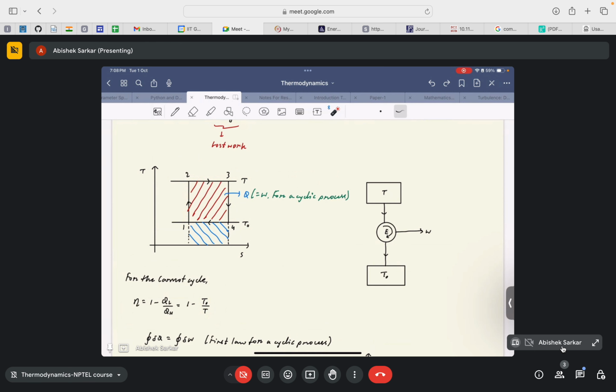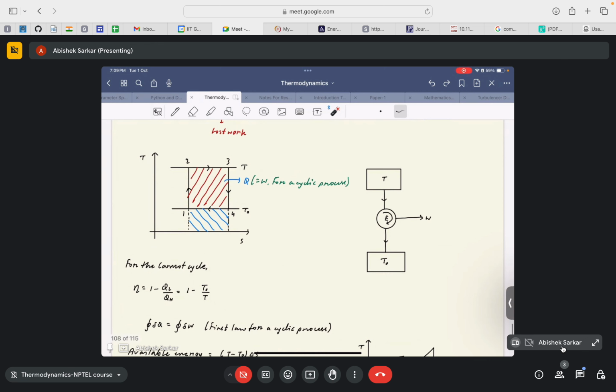And requiring that very scenario of achieving a cooler temperature than ambient requires some additional work, which, if we add up, would result in a decrease in the efficiency of the net cycle, right? So the lowest possible temperature in an ideal case would be the ambient temperature. So the highest possible efficiency of the Carnot cycle would be in the case where the sink temperature is equal to the ambient temperature. Okay, and that's why it represents the highest possible work that can be achieved from a Carnot cycle.